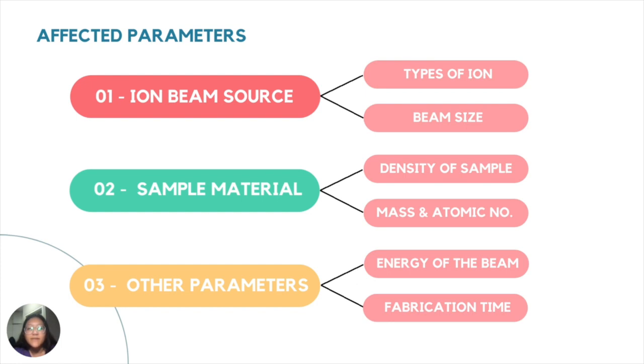Another parameter is beam size. Higher probe current leads to broadening of the beam, which results in poor resolution. Also, larger probe current will reduce current density, which results in lower brightness. Instead, with a small aperture, there will be a smaller beam current, which implies that it is low, but will get a narrow beam, which gives high resolution. The current density might relatively come with the beam size. With a high concentration, there will be a stronger repulsion, causing energy spread and resulting in bad resolution ultimately.